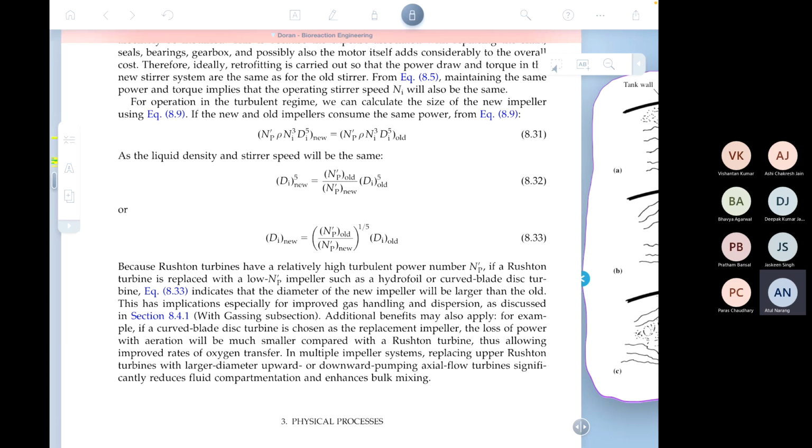So I gave you two simple examples in heat transfer and mass transfer by using purely geometrical arguments. The heat generation increases with volume, the heat dissipation changes with surface area. Therefore, you will have problems on the large scale unless and until you start introducing cooling coils or something like that into the bulk of the medium.